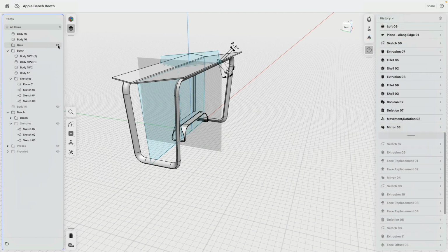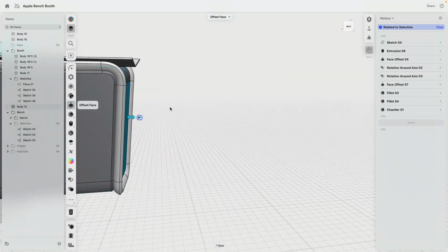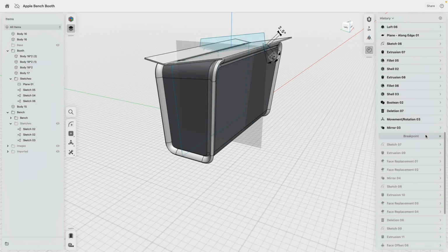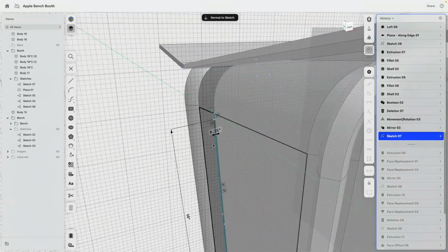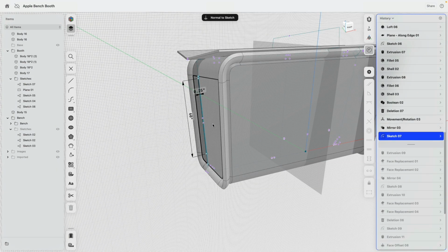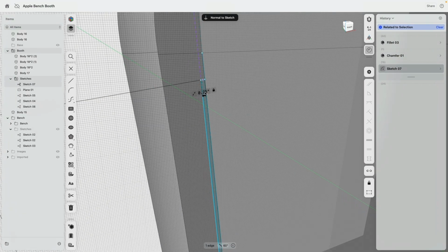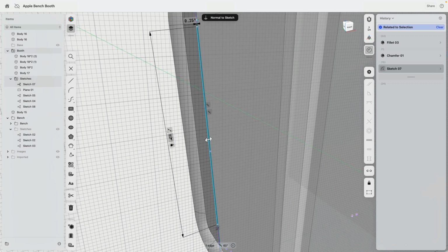I needed to bring this body back because you see that it is rotated. And what I did was I created a new sketch. There we are. I drew a line on this flat face where it intersects, with a thickness of 0.25 of an inch and 60 inches long, this line parallel to here, the other perpendicular.